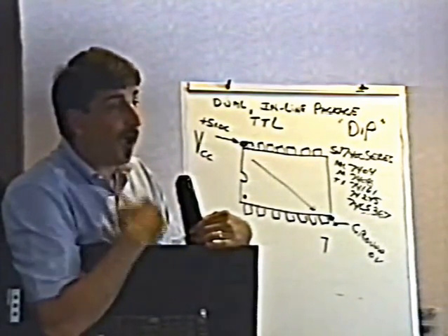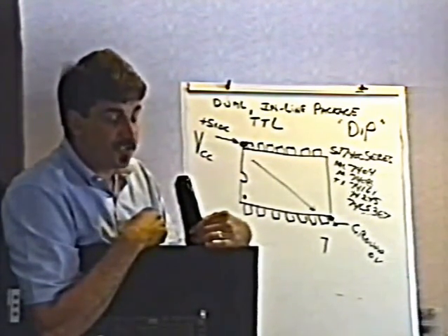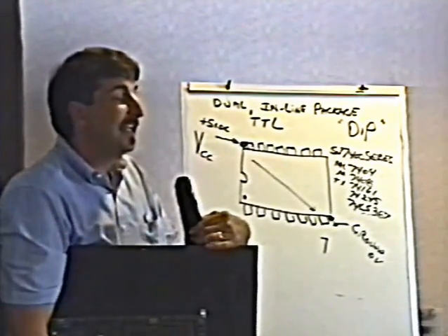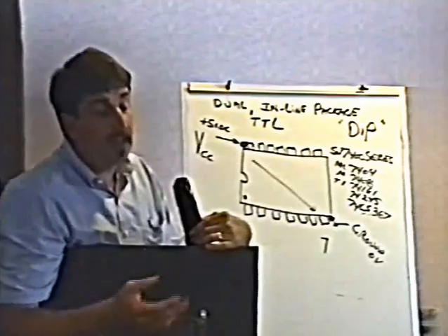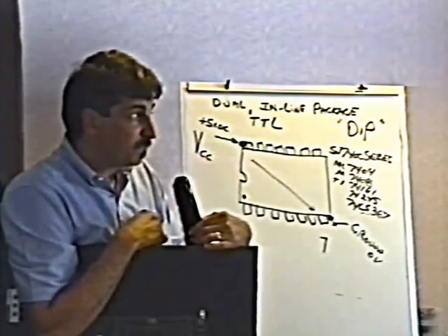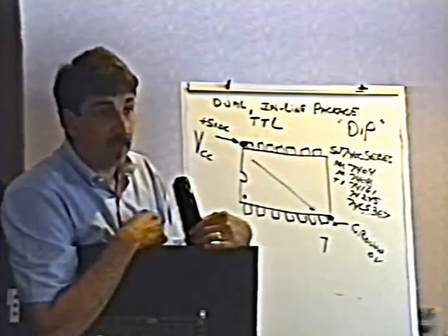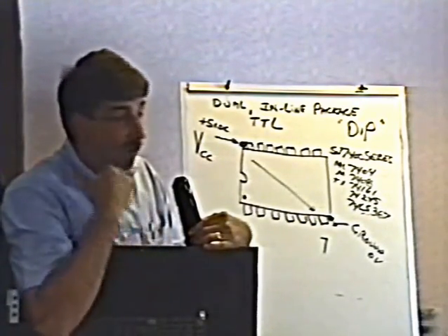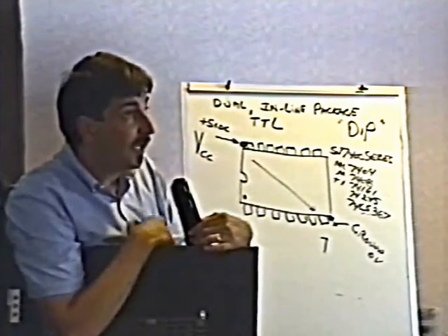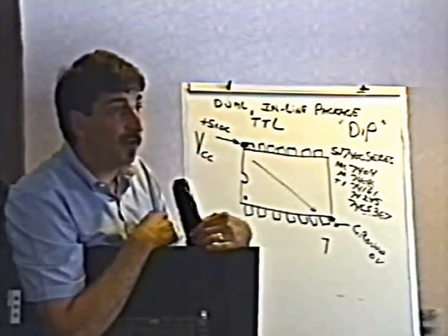When you have weird problems on the board like the one I just showed you, despite the fact that you might measure the 5 volts and it might be perfect on the board, it's not a bad idea to take 10 minutes and throw in a new power supply first. Now, I got to admit that I don't do this. I really don't, because most of the time when you have problems like this and the 5 volt test's okay, it is the board that's bad. But sometimes it's the power supply and you can't figure it out.